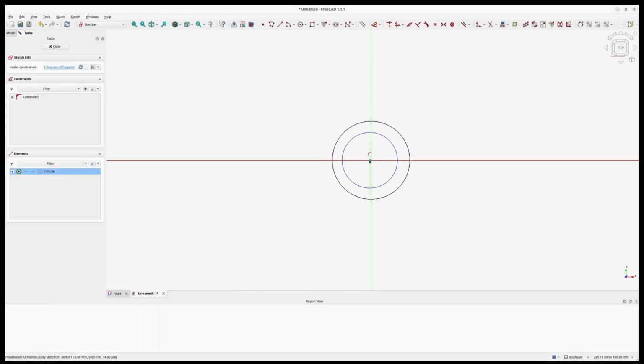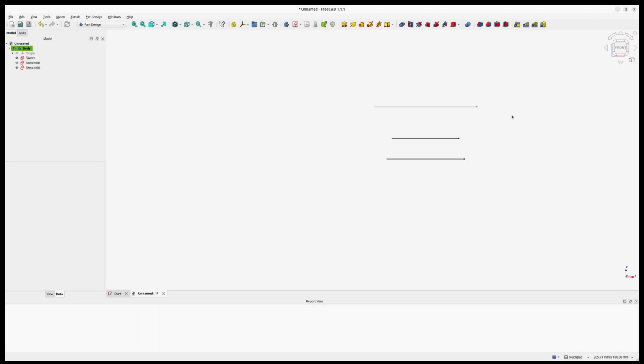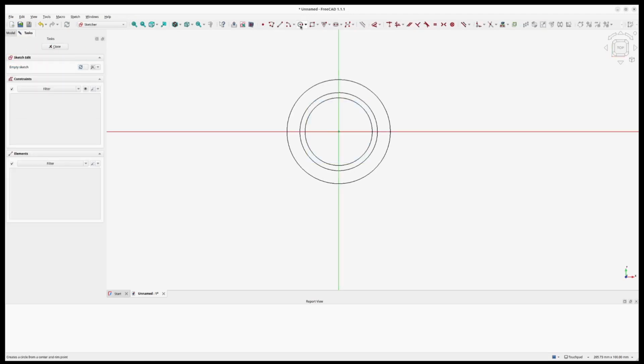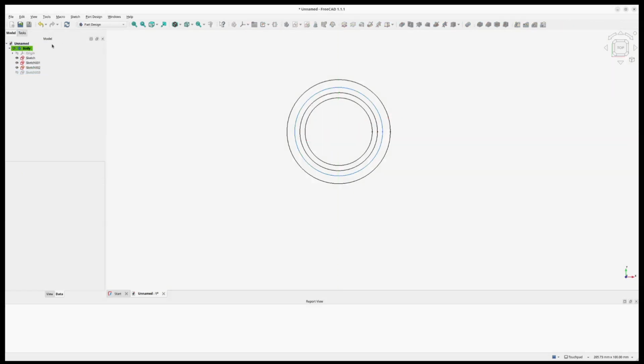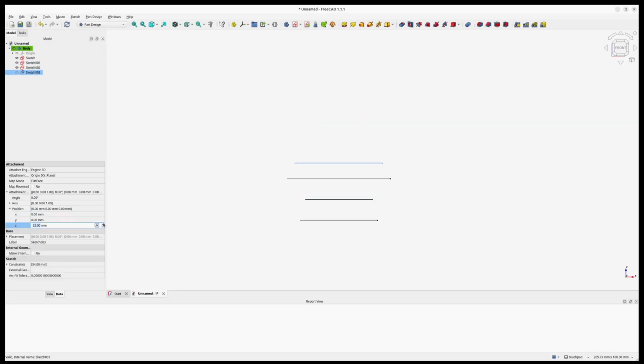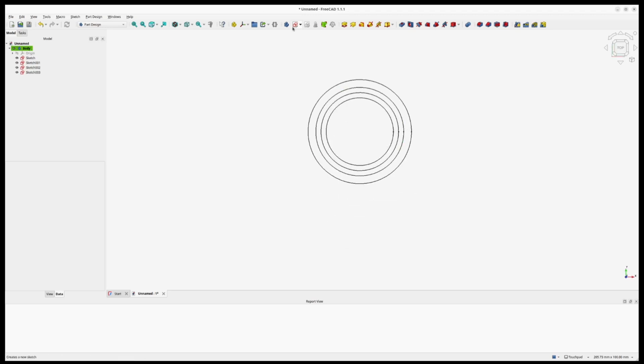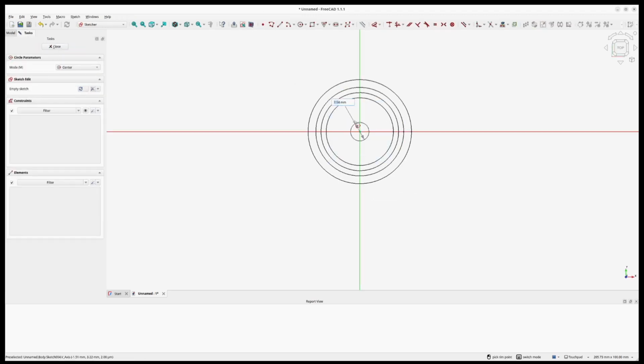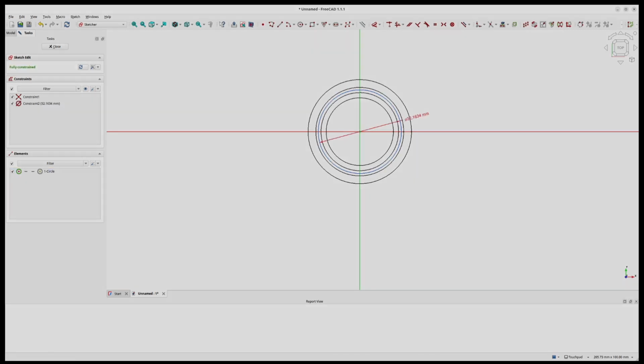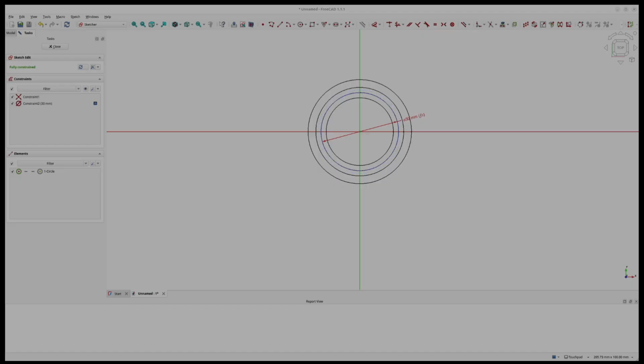Then I proceed to create several sketches with circles all aligned in the center, so they are coincident but with different diameters. And I use the base diameter as reference to create smaller and bigger circles. Then I select the sketch and change the Z position of the placement of the sketch so that they go up and down, and then I can create a shape that I want for my vase.